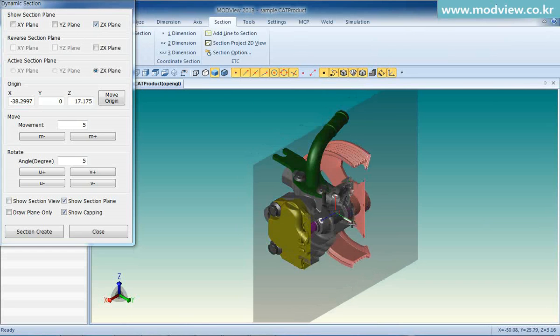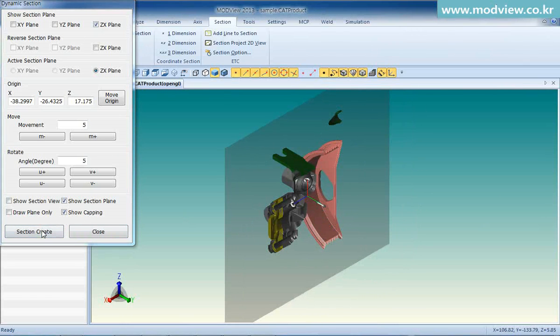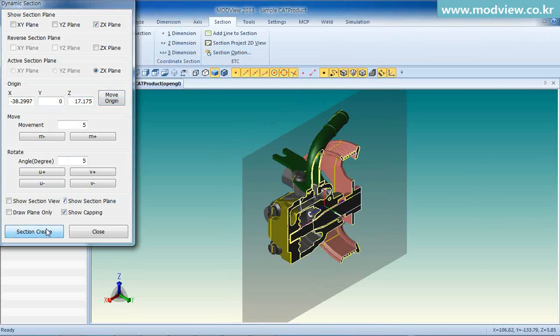First, with a fixed reference plane, you can move the virtual axis to do the cross-section continuously while moving freely. Enter the coordinate values as the reference of the dynamic plane section, and the cross-section operation at that position is possible. In addition, the cross-sectional shape can be cropped in real time at the position.